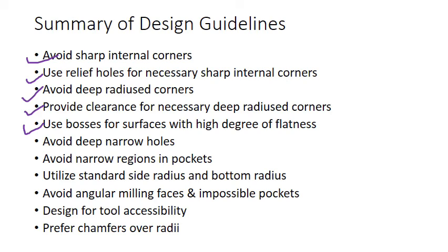Deep narrow holes should be avoided. Narrow regions in pockets should be avoided so as to provide sufficient space for the milling cutter to move. Standard side radius and bottom radius should be utilized. Angular milling faces and impossible pockets must be avoided. Designs should be such that the features are readily accessible by the tool, and chamfers should be preferred over radii.